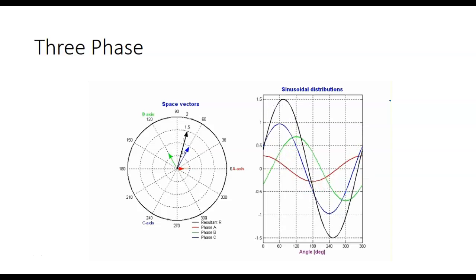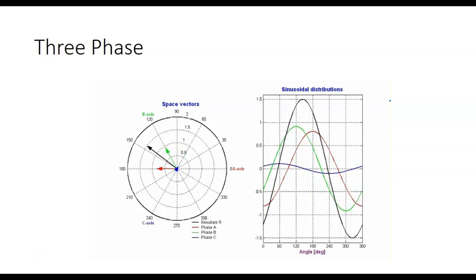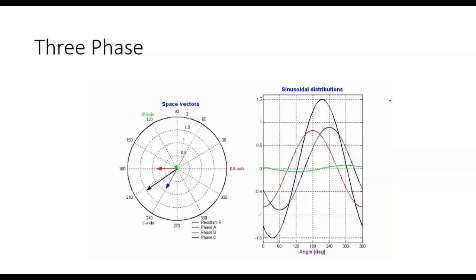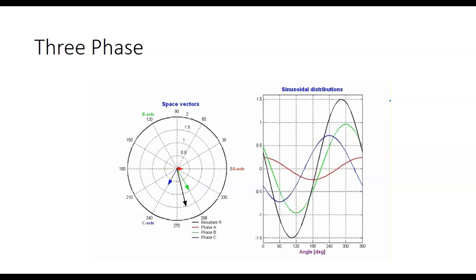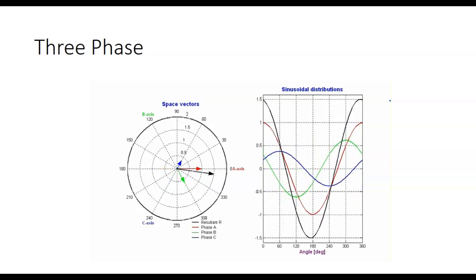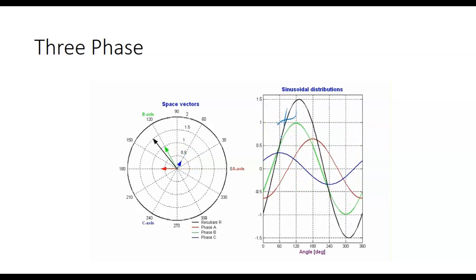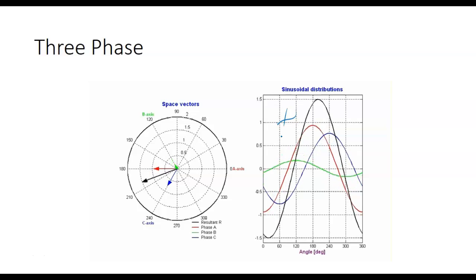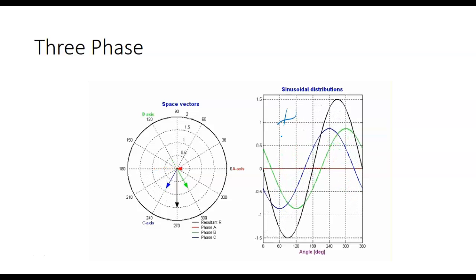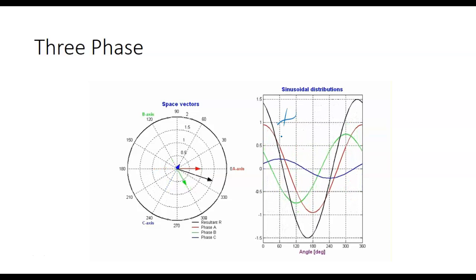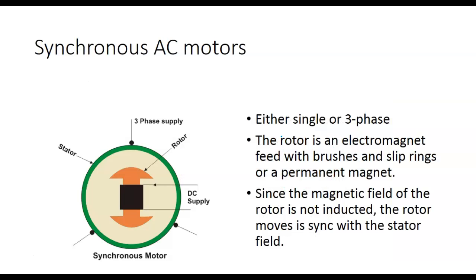So this shows you 3-phase and how it rotates. So you can actually see the power doing what? Moving, right? See the power right here? So the advantage of 3-phase is it automatically creates a rotating field for your armature. How do you reverse them? Anybody know?